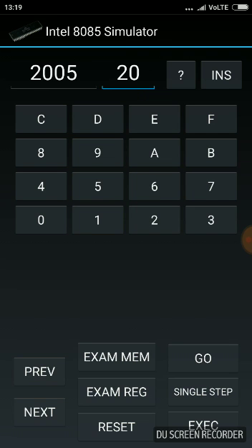Right, now I will set up the counter. For setting up the counter, I will choose a register and move the decimal count of 16 into the register. The corresponding hexadecimal number is 10H. The next memory location is 2006, and I will use the MVI instruction whose opcode is 06, MVI B, and I would move the hexadecimal number 10, which when converted into decimal is 16.